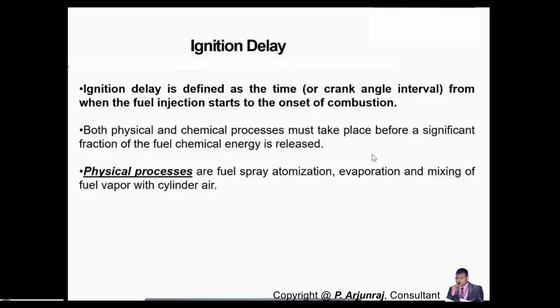When I say physical delay or physical process, the fuel spray atomization is the physical delay, and the evaporation takes some time. Atomization, evaporation, and mixing of the fuel vapor with the cylinder air, the air in the combustion chamber, take some time. That time is nothing but the delay, or the physical delay.